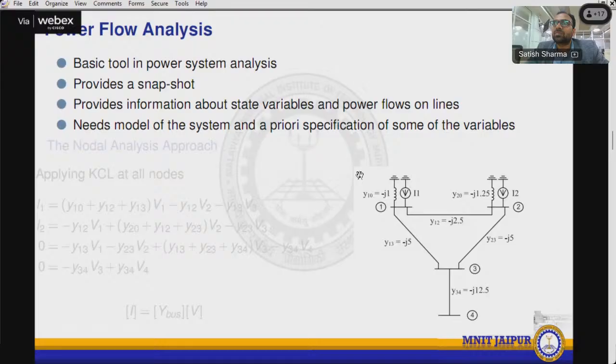Sir, the Vi into Vj product is nonlinear. So we can assume another variable and make the limits in different forms. I agree, but if we relax them to make it linear, that we have already discussed. DCOPF is a linear form of ACOPF only.